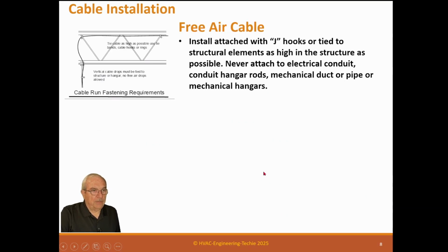Okay, free air cable. Now, free air cable is just the cable you run, and if it's in a plenum, it needs to be plenum rated. If it's not a plenum, it doesn't matter. It can be regular cable. But you always run the cable, you need to attach it with J-hooks, or you can wire tie it right to a member, but always tie to a structural element as high in the structure as possible.